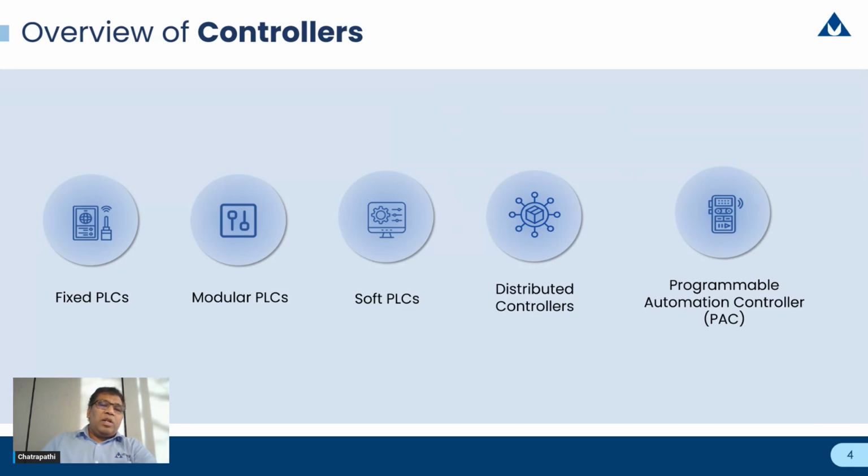And then the modular PLCs come with different modules to be attached to the CPU itself, such as a communication module, the power supply, and different IOs. All these can be added or removed in a very flexible way. These are highly scalable and flexible, and they are suitable for very large and complex applications as well.